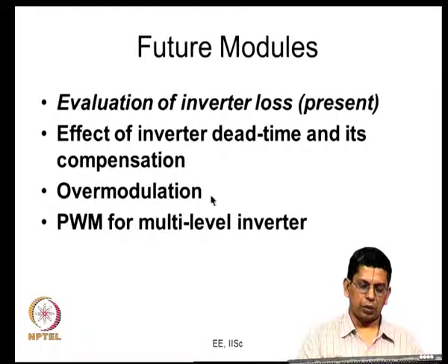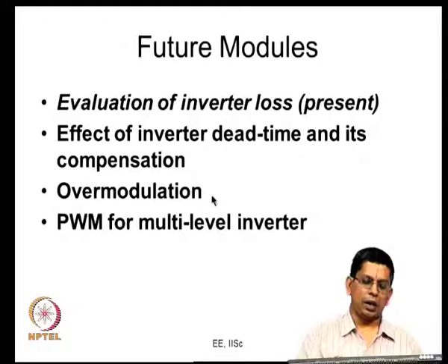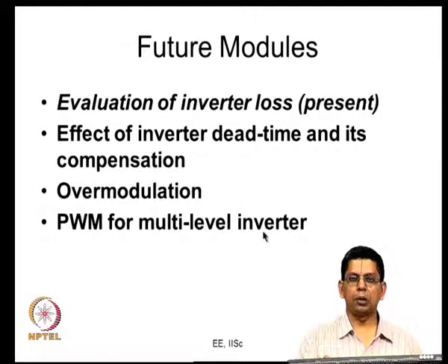Again we would look at over modulation, where we operate not in the linear modulation zone, but go into a non-linear modulation zone all the way till square wave mode or 6-step mode, and then the final module will be PWM for multi-level inverter.